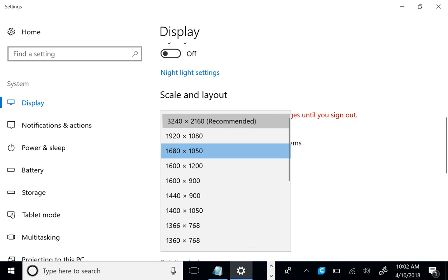And now you could add in your custom print settings over here. You can set things like how thick are the walls, how high are the layers, what infill percentage am I doing, what material am I printing in, what temperatures do I want things to be, right? The infill is interesting. Where's my layer view? So if I go to layer view here, and then scroll down through the layers,